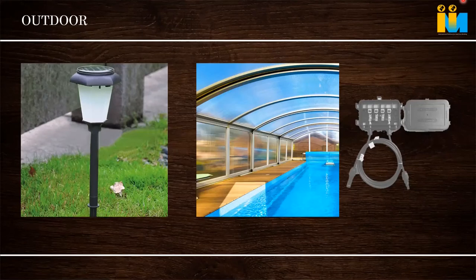After a cycle of 100 hours, 200 hours, a heavy load of light is given. Suddenly it will be immersed in water, then again it will be heated. The results will be correlated, like 200 hours of xenon arc will be equivalent to 1 or 2 years. The more severe the testing, the more data points we get, and based on that we can take a call.